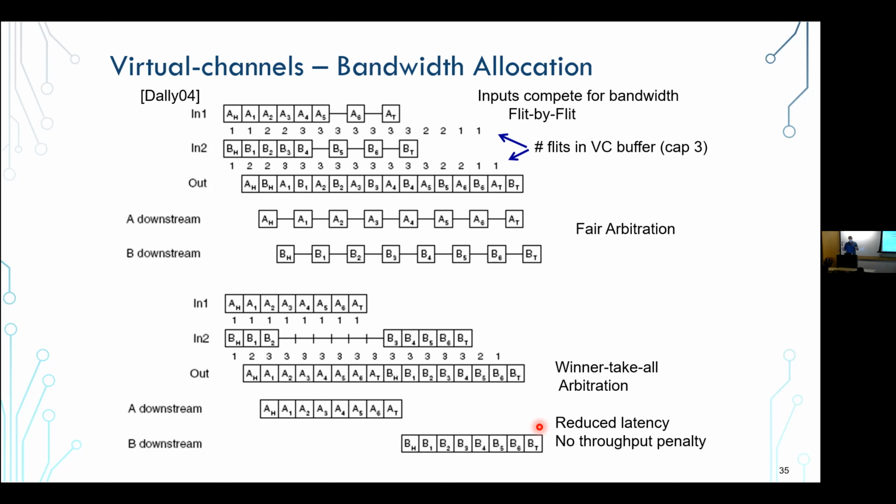As you're architecting the router, you want to know in how many cycles you'll actually be able to traverse a router. And these types of decisions and arbitration can take some amount of time there. So you want to make sure that happens really fast. But if it has to happen very fast, it can't be really complex, meaning you can't take all sorts of variables into account. It has to be some simplistic scheme of determining arbitration, yet satisfying the overall application goals.